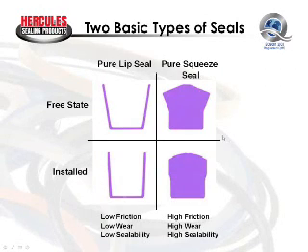With our pure squeeze seal, however, when we displace the seal material, changing the seal shape, it increases a lot of radial force at the seal lip sealing surface interface. So we achieve a very high degree of sealability at low pressure, but to achieve this sealability at low pressure, we have a high degree of friction and a high degree of wear.